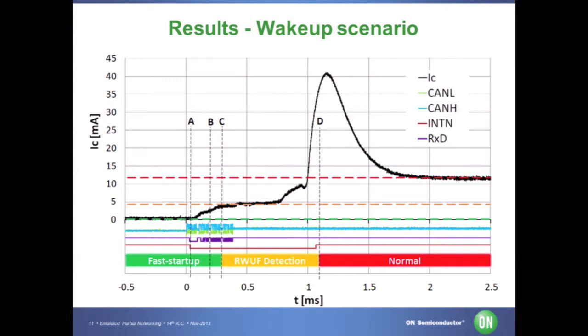Then the microcontroller is switched from pseudo-stop mode to the wait mode, and it switches the receiver to the receive-only mode, and the receiver starts reporting the data received from the bus to the microcontroller.